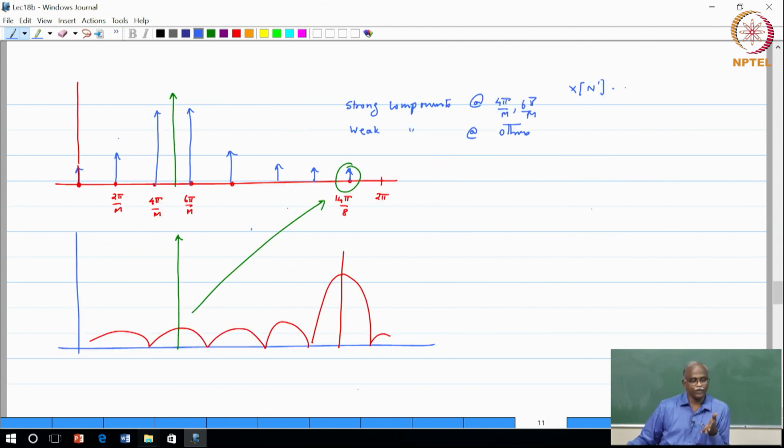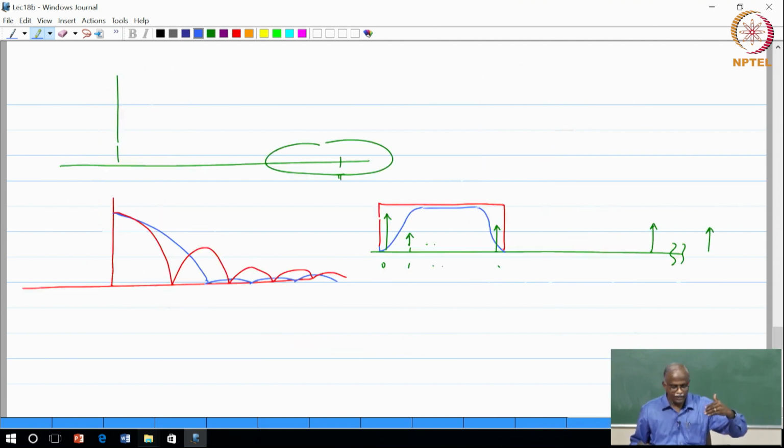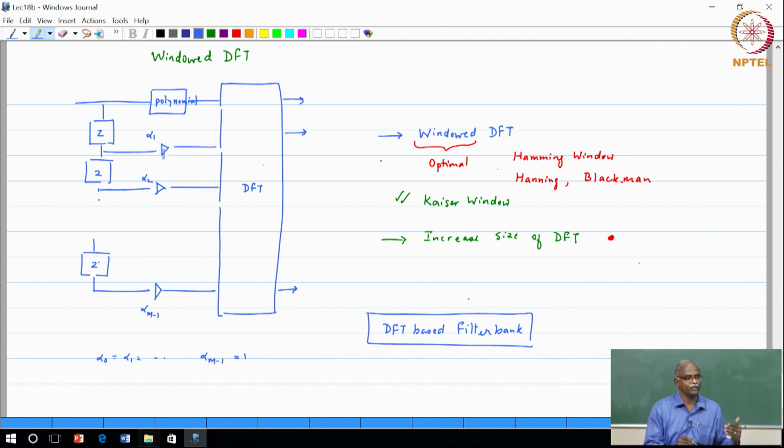Yeah, definitely, because for some case, if this becomes one of your DFT points, frequencies, then you will get a tone. All the others will have zero crossing, so therefore you will actually get precisely the spectrum that you are looking for. Yeah, so basically if you take a filter and you take its polyphase components, each of these will be a polynomial, those will be the polyphase components. So, in the general case, those are polynomials, but it is not a random polynomial, it is a polynomial that is derived from a filter impulse response.